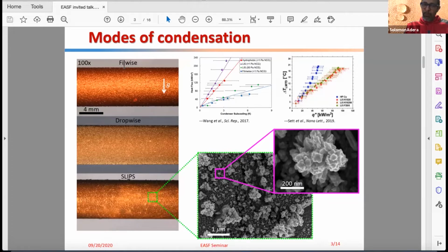This can be improved by hydrophobizing the surface, in which case vapor condenses by forming discrete water droplets that leave when they reach the capillary length for water, about 2.7 millimeters. What that means is the condensate leaves the surface earlier and doesn't form a continuous liquid film.